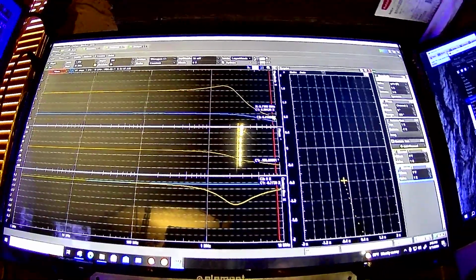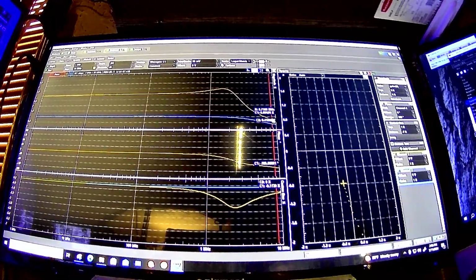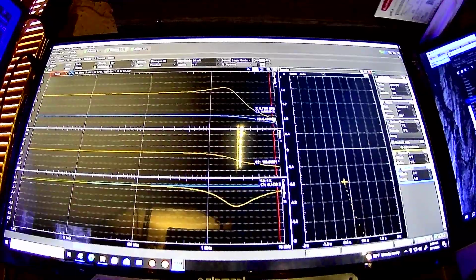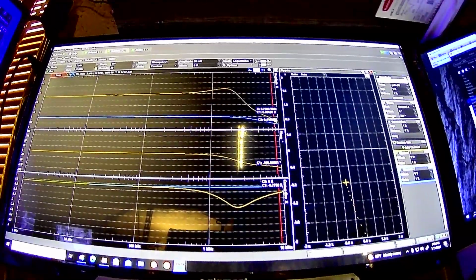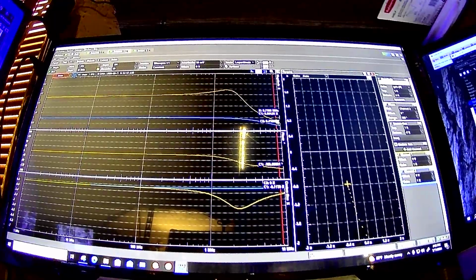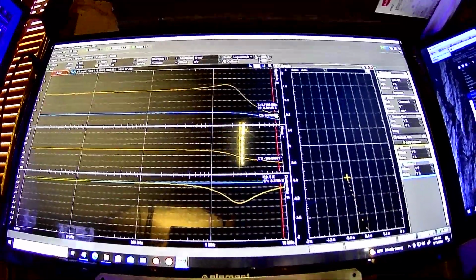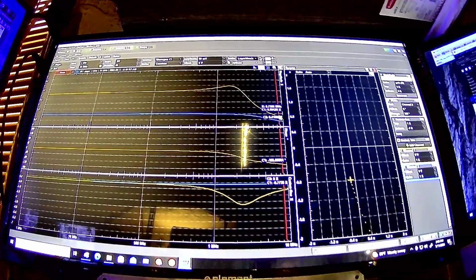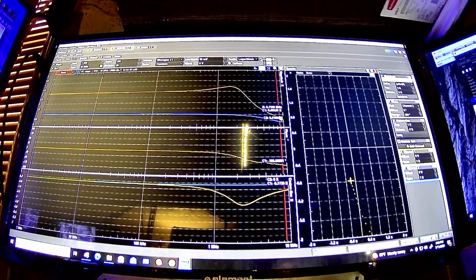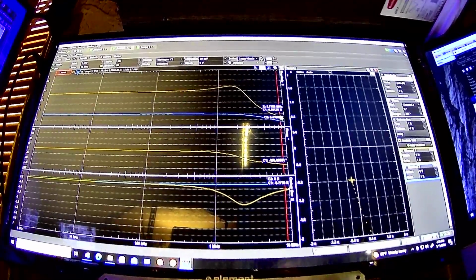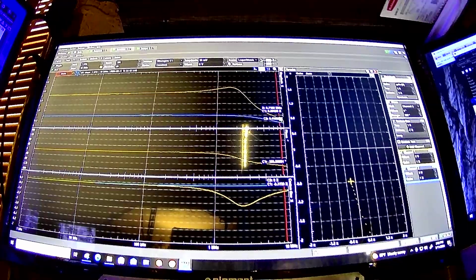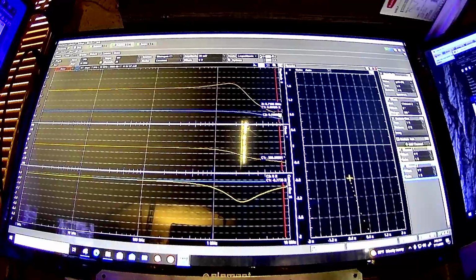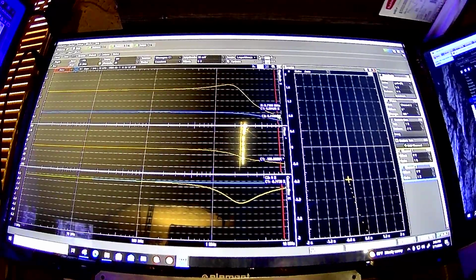When you put a capacitor like that across your feedback resistor to filter out high frequency noise, what you actually want is that capacitor's reactance to drop below the resistance of your feedback resistor, so you in effect give the amplifier below unity gain, right? The higher the frequency, the lower the impedance across the capacitor, and that effectively starts cutting your feedback resistor towards zero as your capacitive reactance diminishes with higher frequencies.